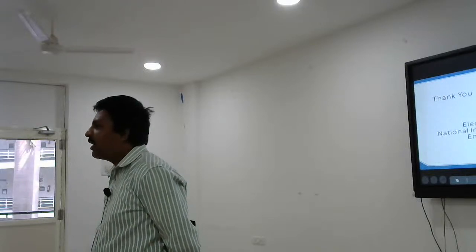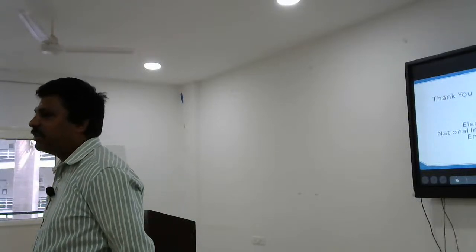Actually what our students will do, when somebody is doing power converters, they do it on a zero PCB. You can take a simple breadboard and just do some small gate drive circuit, and then you implement a simple small switch. First you start with a switch, a simple battery, then switch, then load. Then you try to control the load with a simple gate drive circuit. Actually what I have drawn, that's a basic gate drive circuit.